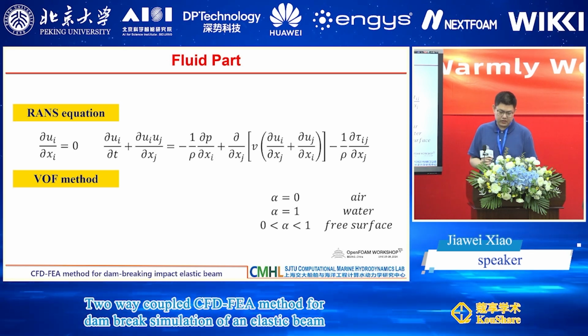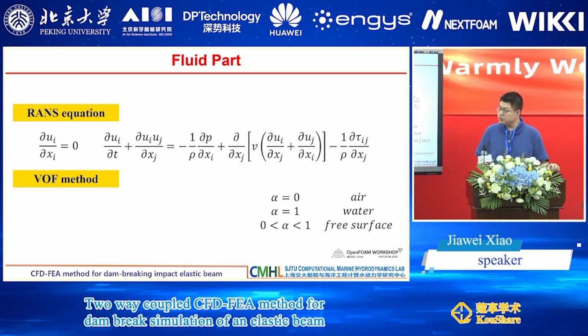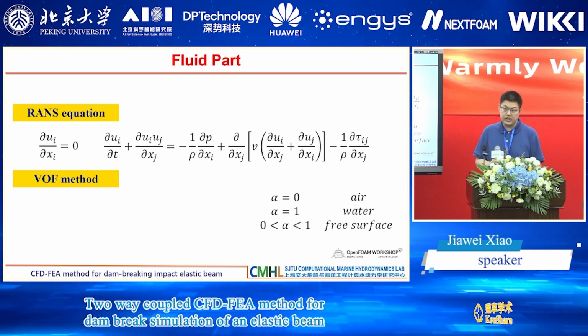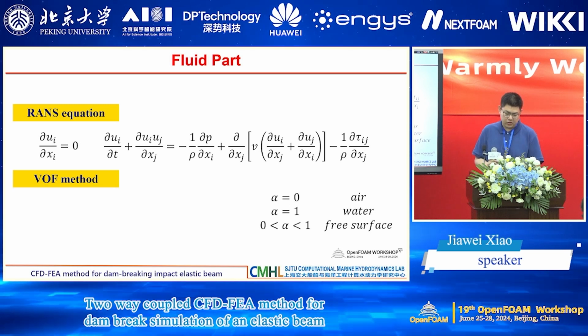And in the Reynolds-averaged NS equation, the tau term replaces the Reynolds stress, which requires additional properties to close the equation. So that led to the creation of many turbulence models. We use the K-omega SST model, which is a common choice.